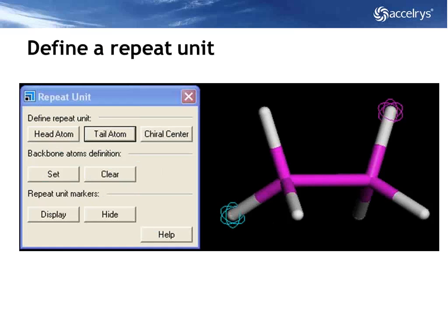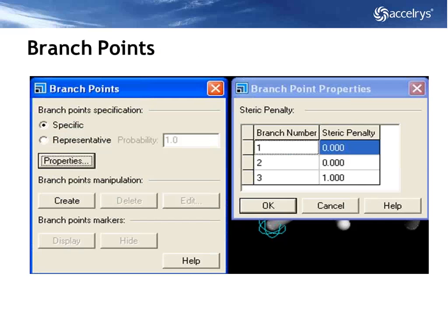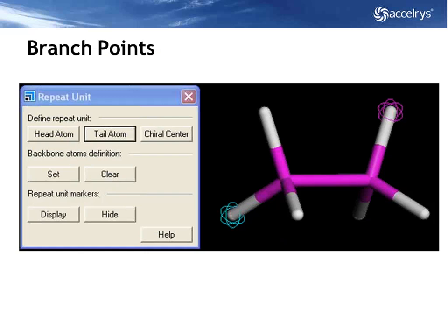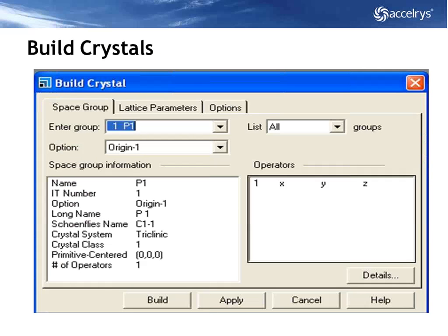As I've shown you, dendrimeric structures. You can define repeat units for that construction, dead easy. You can define branch points. So here you see I have a head and tail branch point. If I so wish to build a repeat unit, force field minimize it, quantum minimize it, and then define a polymer from that, I can then choose exactly where that extends within my polymer frame.